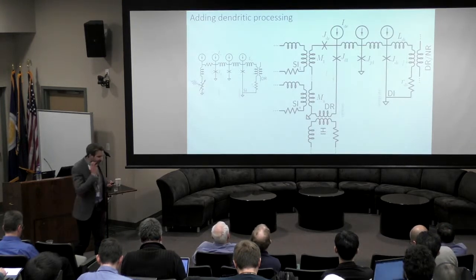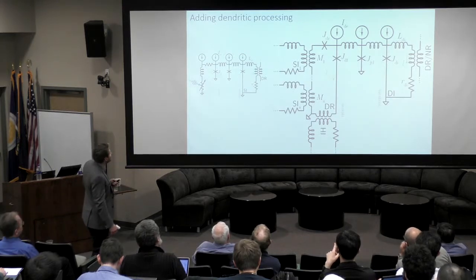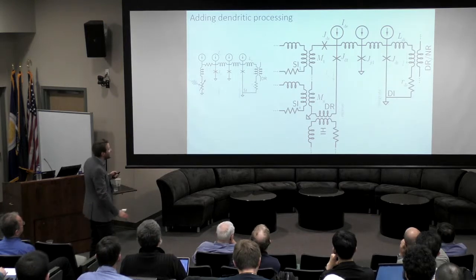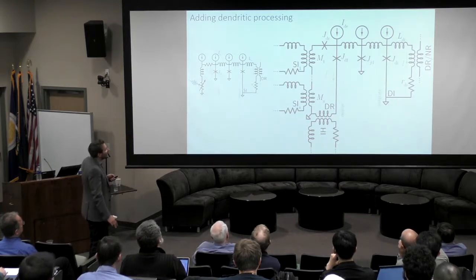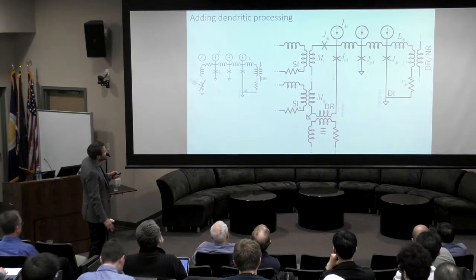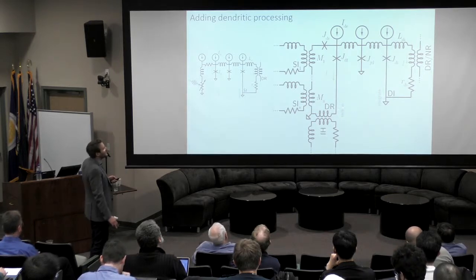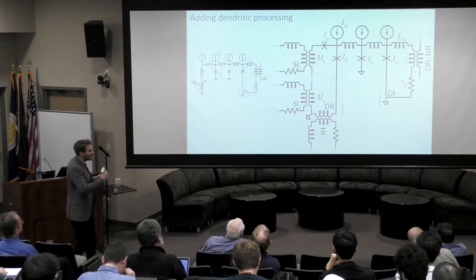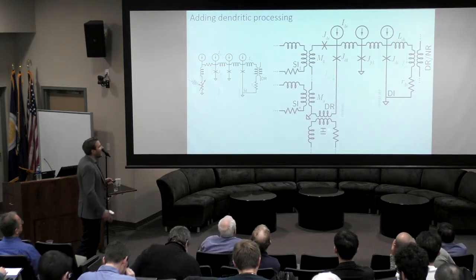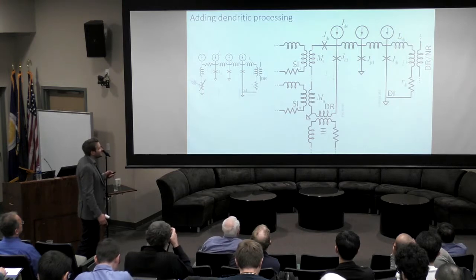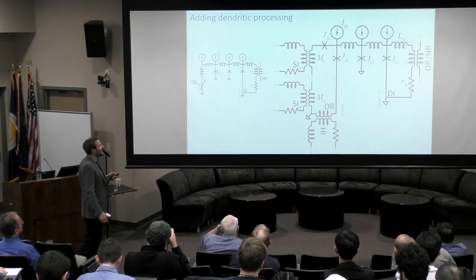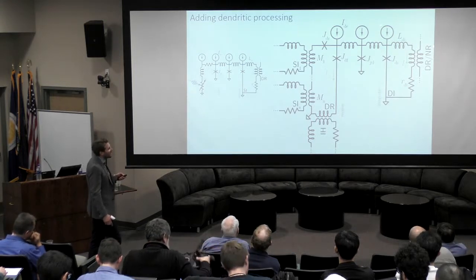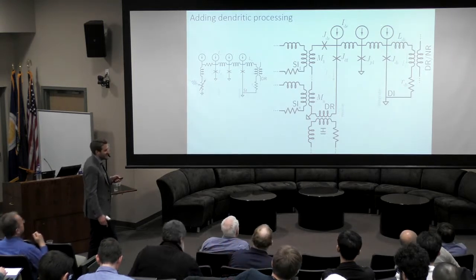Okay, now I'm realizing just how many circuits there are up on the screen. This is the synapse that I talked about before, and everybody understands it now. So if you just quickly look over here, it's actually pretty much the same thing. I'm talking about a dendrite now, but it's doing the same thing. You have a receiver that takes in inputs from all your different synapses, maybe 1, maybe 10 of them. And when the current from all of those gets mutually inductively coupled into this loop and exceeds the dendritic firing junction critical current, then you pop a bunch of current into this loop, the dendritic integration loop.